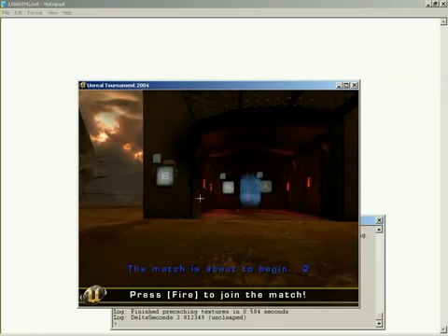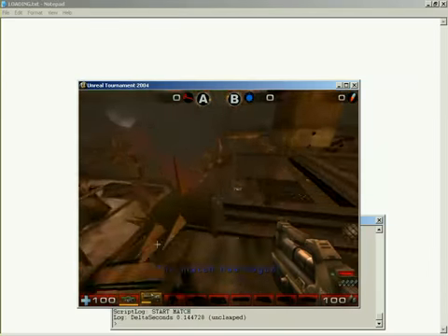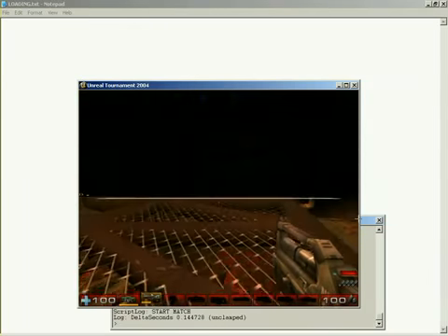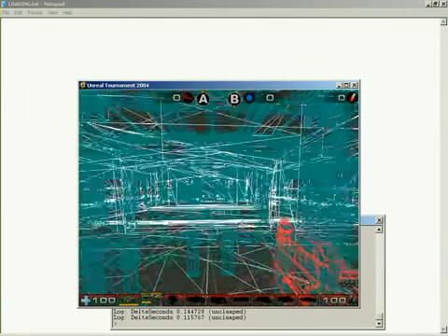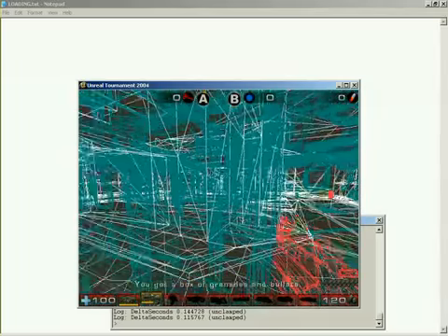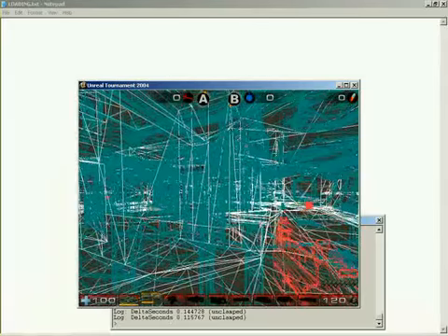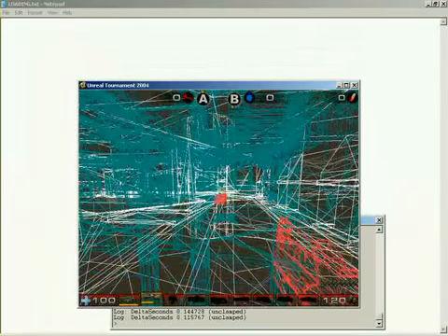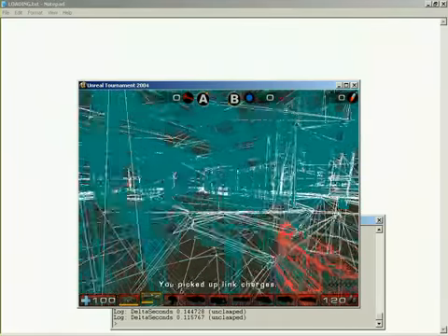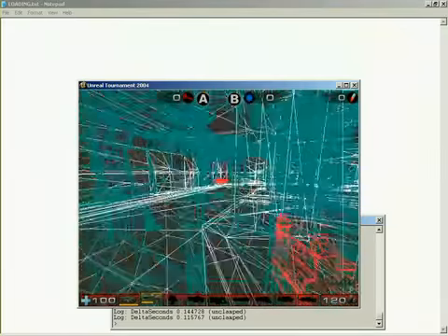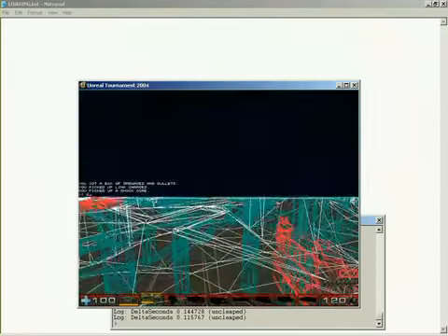First thing, I'm going to jump down to that area and then activate R mode 1. All right, there's the doorway. R mode 1. So yes, we have wireframe, but we are still on the outside. Let's walk in. Even when we're on the inside, looking very close to a wall inside a tight area, we're drawing what's behind the wall, the rest of the room, what's outside, the train in the distance. Even things which are technically occluded are still rendering in, and we can still see them all. Again, there's no zoning in this area, so there's no clues as to where the engine should stop drawing anything.